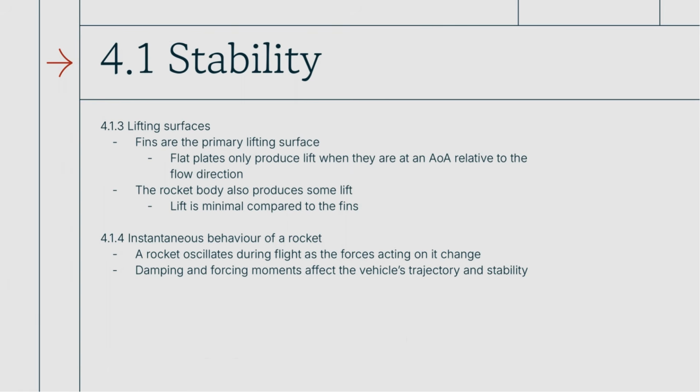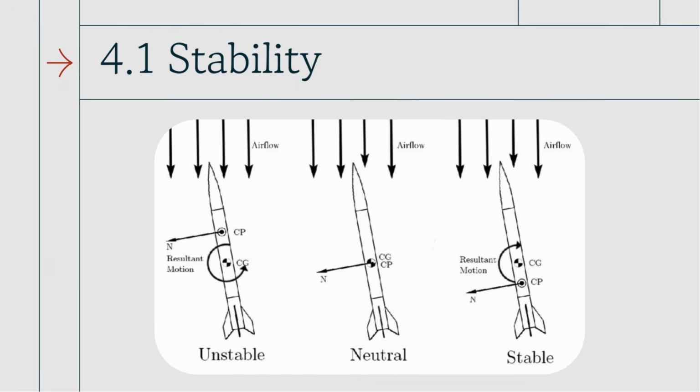Yes? If you had the center of pressure and the center of gravity at the same point, what would happen? So, I'm getting there. Basically, there are three different cases. You can have the center of pressure above the center of gravity, at the same spot as you asked, and behind it. If the center of pressure is above the center of gravity, that means almost all of the forces on the vehicle are acting in front of the center of gravity, and they're trying to push the vehicle to one side. What happens when this vehicle is at an angle relative to the flow and the center of pressure is up here?